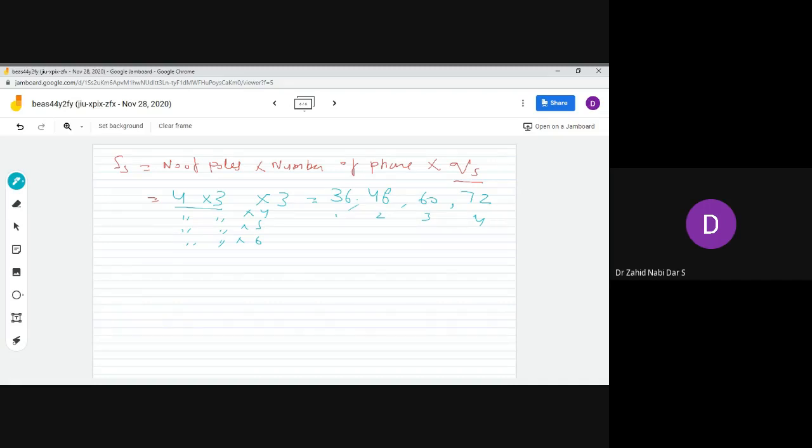Slot pitch for semi-closed slots is less than 15 millimeter. A big machine is an open type of machine. I have already discussed this in the theoretical part, and a big machine means it should be greater than 100 HP. Some numerical value is there, please look into that.